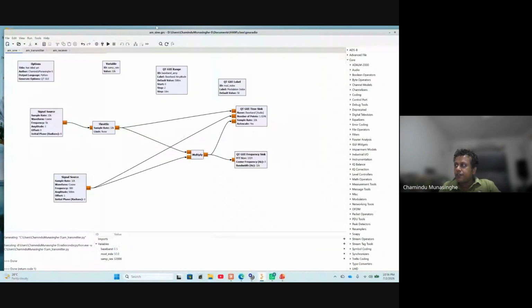Now, the software I am using is what we call GNU Radio Companion, which lets me write GNU Radio code using a GUI, kind of like a flow graph interface. This is what we call a flow graph. We connect these source blocks together, so signals flow from one block to the other, connected blocks. Actually, what this does is generate a Python file, Python code that actually runs.